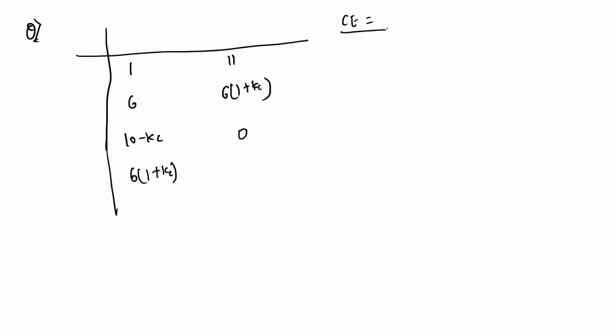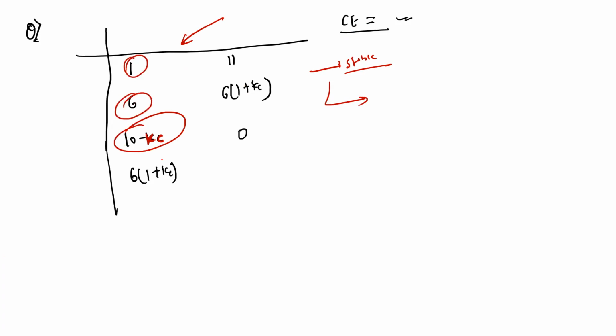So they are telling you that a closed loop response system has a characteristic equation, and from the characteristic equation we have formed a Routh array. We want to understand, if the system is to be stable, what will be the maximum value of Kc. So what should we do? The coefficients of the first column should be positive. This one is positive, this one is positive, and this one has to be positive.